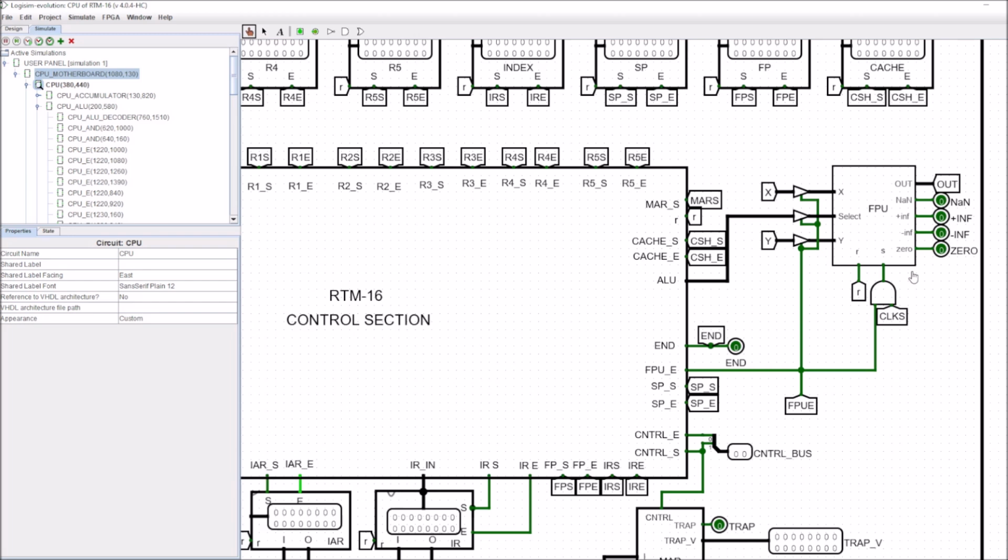It means we can build even more complicated circuits, and we just connect them via control buffers, and we can just open or close the control buffer and use the extra circuit, in this case the floating point unit, when we want it. Now, if I didn't do it like this and I didn't use a control buffer, then the floating point unit would always be working and it would slow down the Logisim simulation, so it would be really unusable. So this is a nice, neat little trick in order to employ the floating point unit.